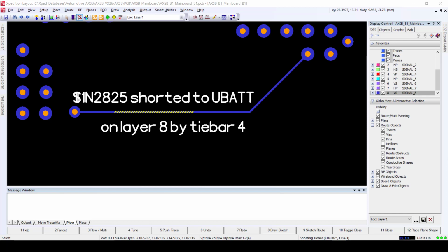There are several scenarios in which a layout designer may need to short two nets together that are not shorted in the schematic. For example, a sense line for a power supply, or multiple ground nets that must tie together for noise reduction. For example, ground, analog ground, and digital ground. Expedition now supports these use cases through the use of new route objects called tiebars.